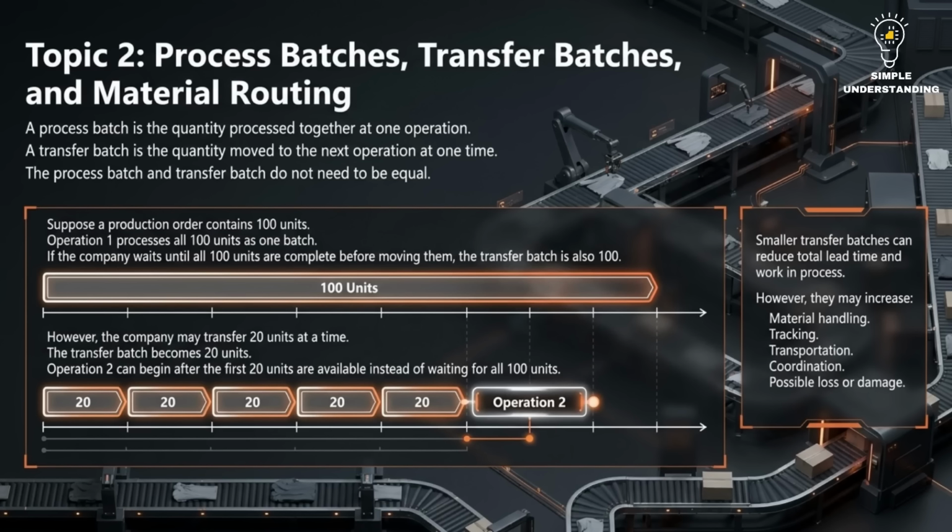Topic 2. Process batches, transfer batches, and material routing. A process batch is the quantity processed together at one operation. A transfer batch is the quantity moved to the next operation at one time. The process batch and transfer batch do not need to be equal.